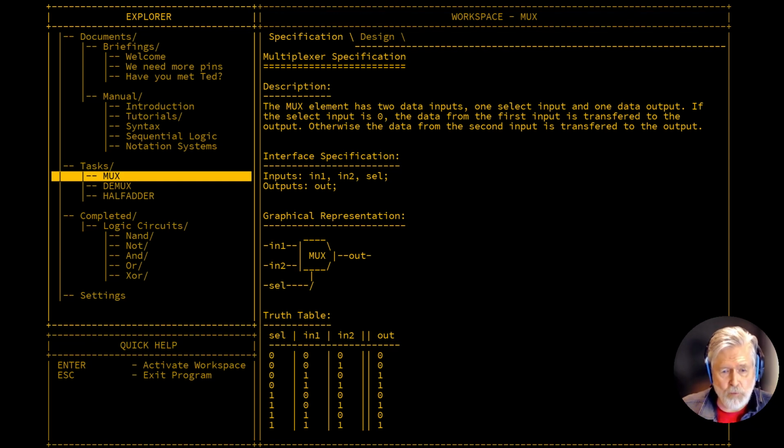When select is 0, you'll notice that the out value is equal to the first 4 values of the N1 pin. And if select is 1, then you'll notice that the out value is equal to the last 4 values of the N2 pin. And that's what we mean by selecting. We mean we're getting those data values from the inputs, either N1 or N2, to the output.